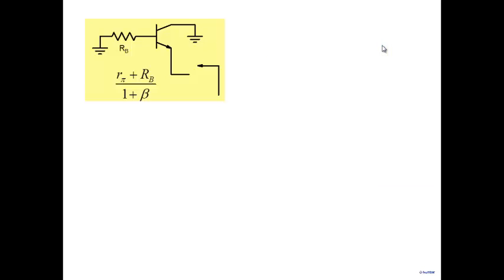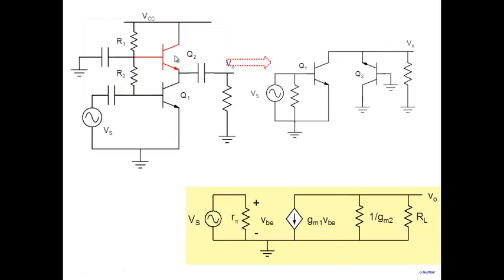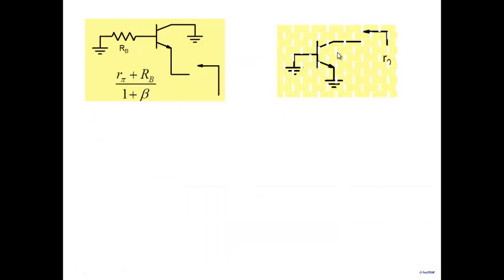So our mistake was that my lower transistor is seeing as a load this one, Q2, but it's seeing into its emitter. And when you see into its emitter, naturally, its resistance is very small and you don't get any gain. So what we are looking for is using a transistor in a way such that it offers a high resistance at this particular point. So we can't connect the emitter of that transistor here. We need to connect the collector here.